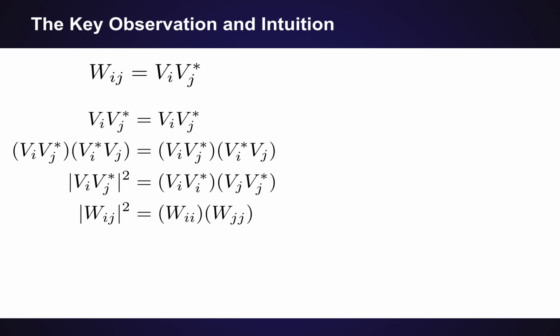And I think it's worthwhile noting that this is a valid constraint for any power problem because we derived it from just the product of the voltages. You could take this constraint and add it to any problem where you're producing voltages and it's not going to remove any solution.